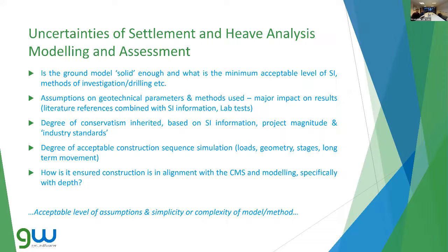Next, this is where good communication with structural engineers comes into play. We need to know how the basement is going to be constructed. If we can get a construction method sequence from them, then that's great, and we can try and tailor modelling to be in accordance with that. But you can't model absolutely everything. So it's a balancing act between efficiency and how much detail you want.